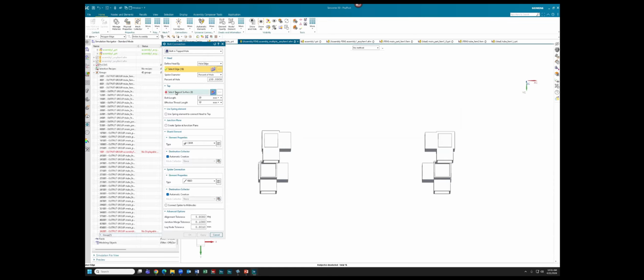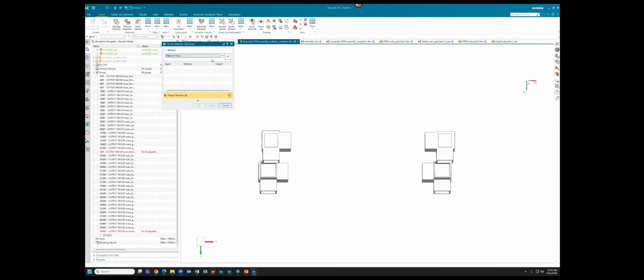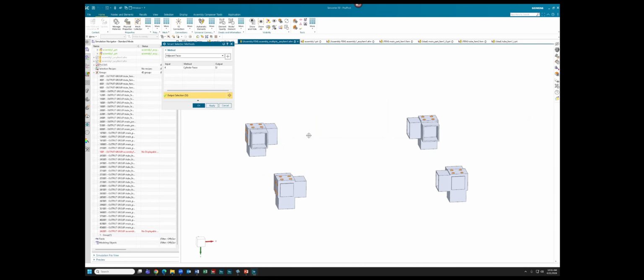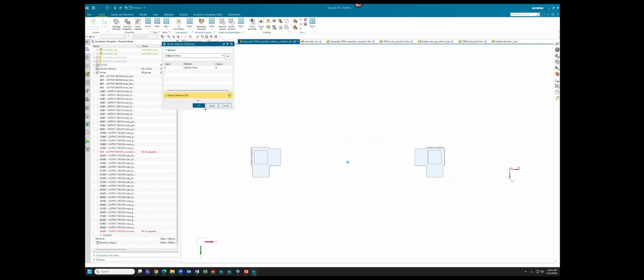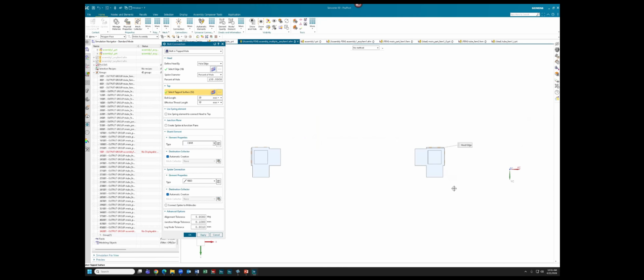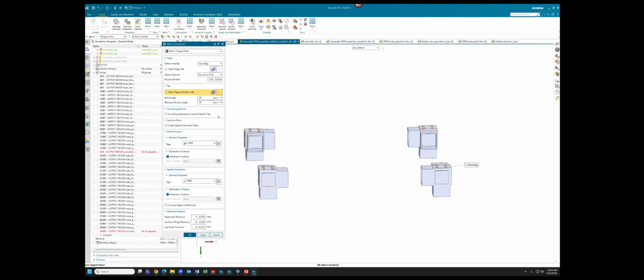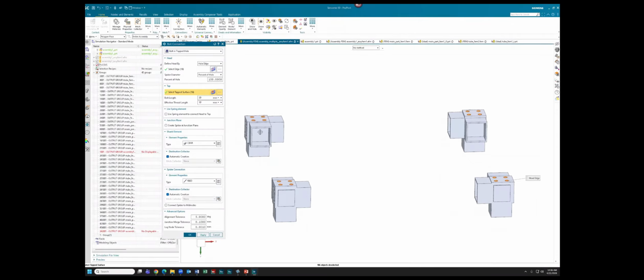And then we can go ahead and deal with the tap surface side. So now the command is looking for cylindrical face selections, so we can essentially use our smart selector methods once again, and it's going to grab all of our cylindrical faces that we want. So you can see just with a couple clicks here, we're able to grab all of these faces rather than having to do more manual operations, which is so useful. Definitely recommend leveraging those smart selector options. So now we have our selections complete.